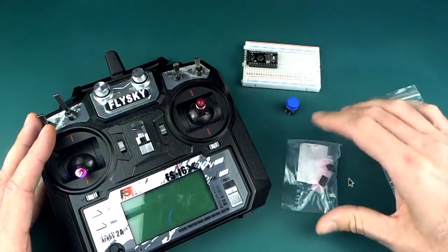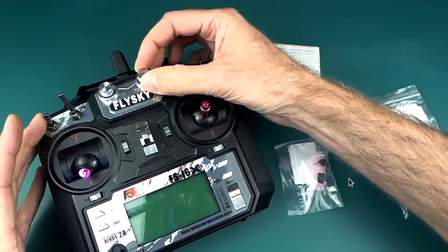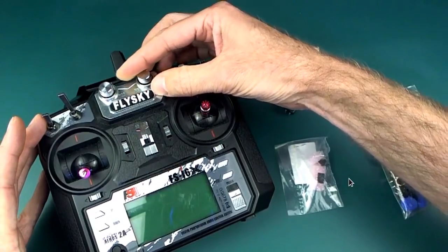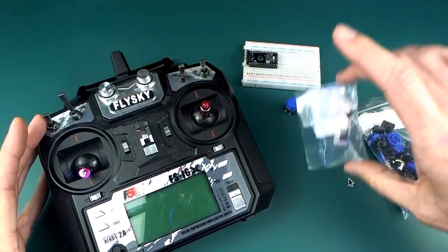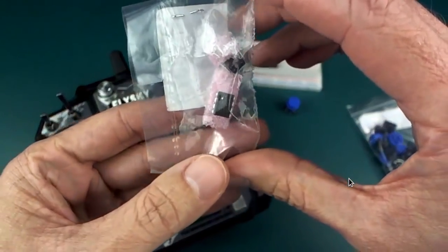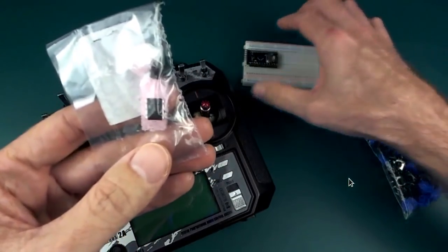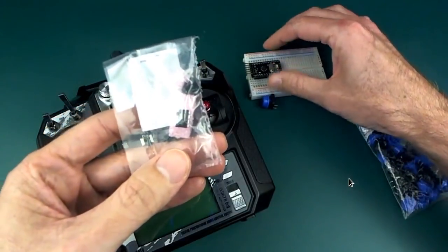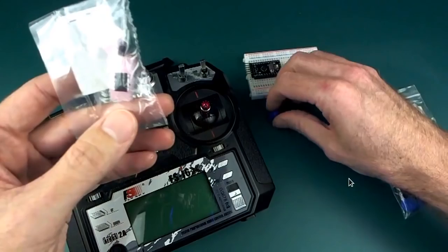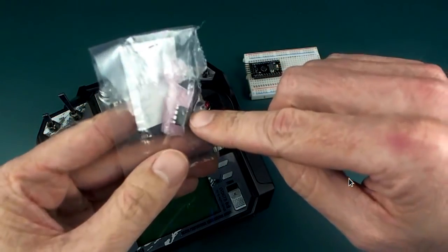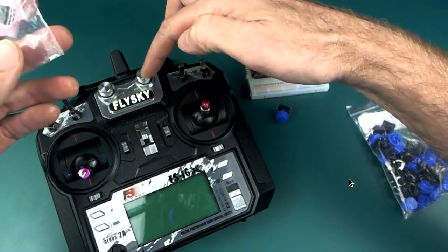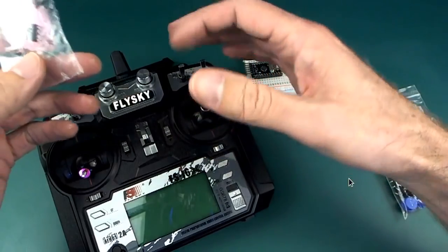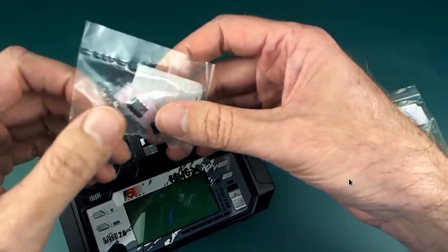So how is this going to work? We need to replace a physical analog potentiometer like this with one of these things here, which is a digital potentiometer. So basically we need to have an Arduino that's going to detect button presses, and this Arduino will remember which button was pressed last, and it will tell this variable potentiometer to send the right resistance to the radio. So the radio is not even going to know that any of this is going on, I hope, but this will achieve what I'm trying to do.